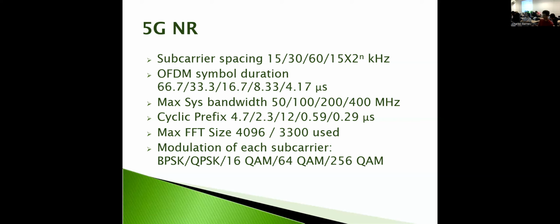So if the variation between the different rays reaching the receiver is such that some take 100 nanoseconds longer than the others, maybe 900 nanoseconds longer, something like that, then the cyclic prefix should be longer than that delay spread, not too much longer, and we can maybe sacrifice a little bit, but it should be on that order, right? That's what's governing the length of your cyclic prefix.